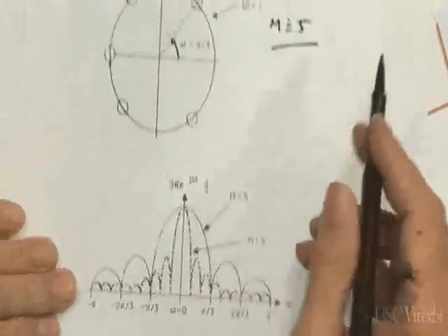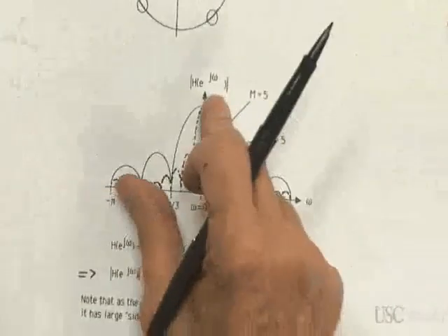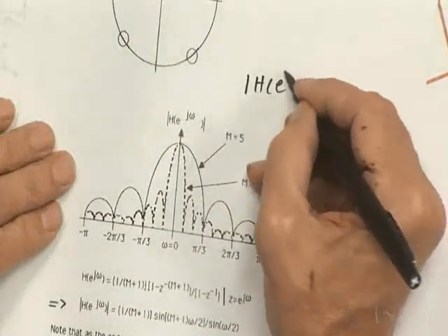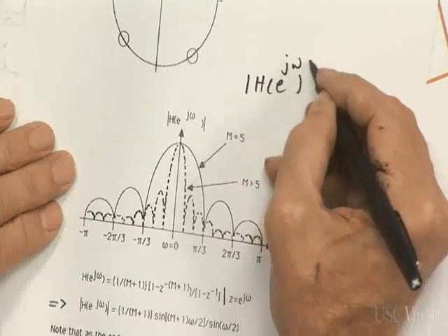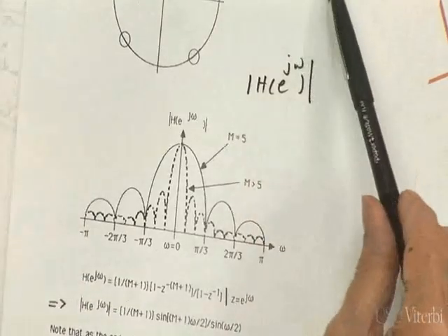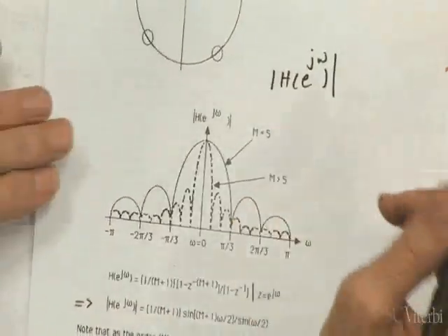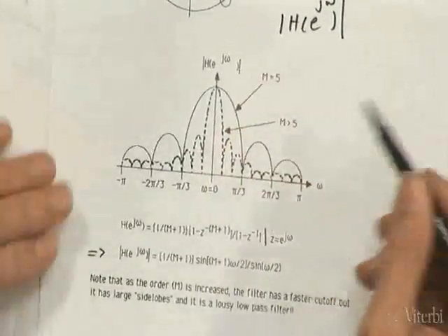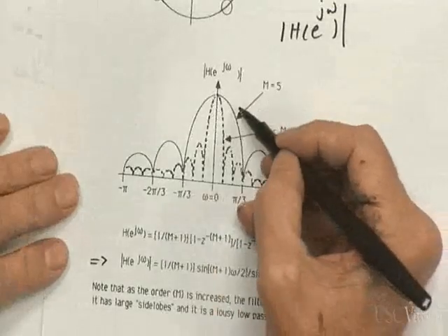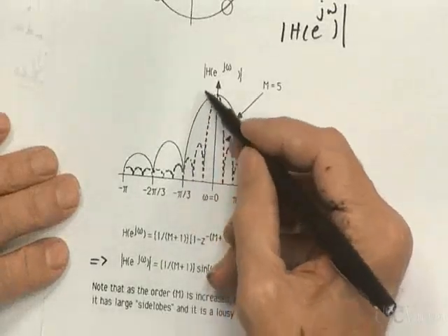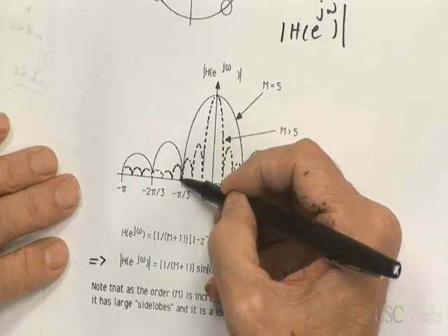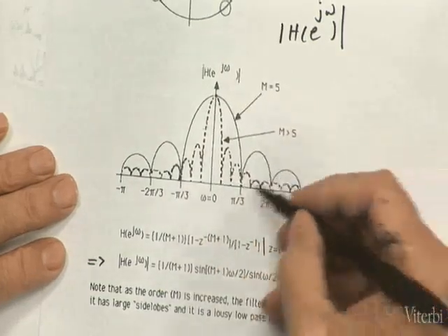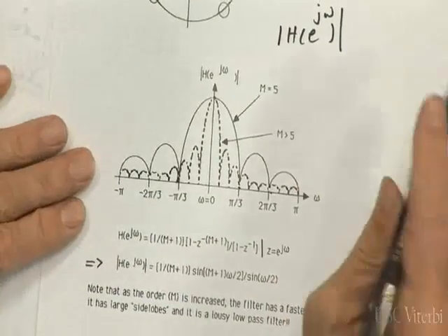Now what I've drawn here is in the Z domain. Here I've drawn the frequency response, the magnitude of the DTFT. I've just let z equal e to the j omega, and I'm computing its magnitude and sketching it here. If M equals 5, you would get a sinc-type plot, where it's 0 here, maximum here, 0 here, 0 here, basically at multiples of pi over 3.